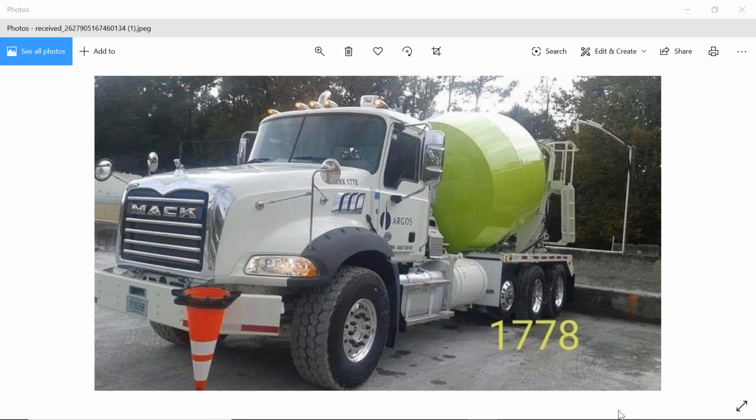Determine the adjustment in pounds: 1,685.286 minus 1,620 is equal to 65.286 free moisture. 5. Adjusted water quantity in pounds is equal to 267 minus 65.286, which is equal to 201.714, which rounded off is equal to 202 pounds. 6. Determine water adjustment in gallons.